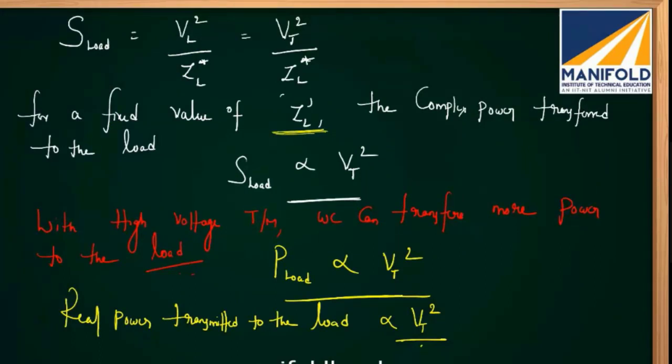Excuse me, sir, I have a doubt. Yes, ma'am. Sir, in the high voltage case, as the current reduces, the size can be reduced, right, for the same power capacity? Yes, for the same power capacity. But while explaining copper and aluminum, we were saying that as conductivity is less, the size is more for aluminum, and that is an advantage. In one place we are saying the size is more, it's an advantage, and in the other case the size is less, it's an advantage.